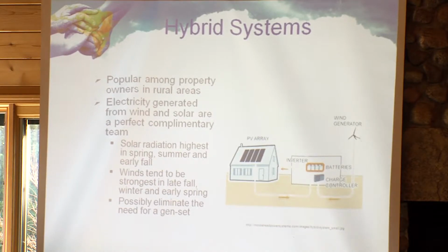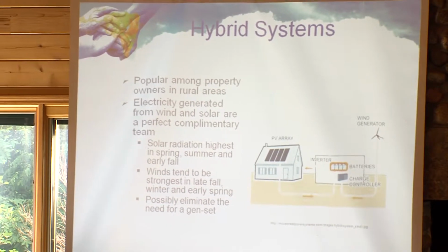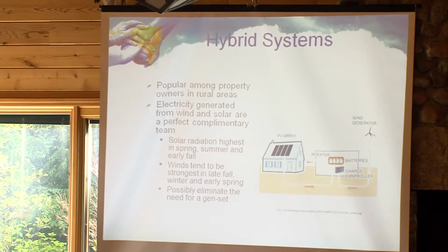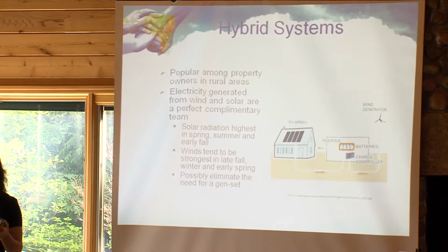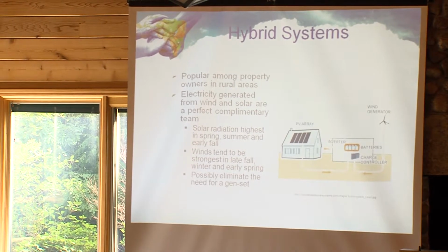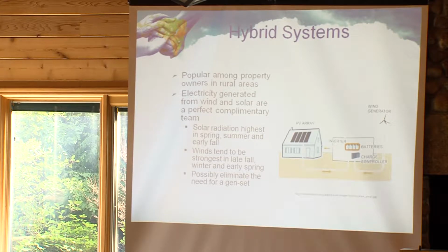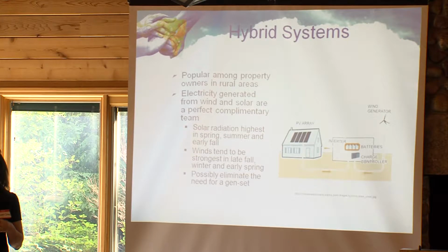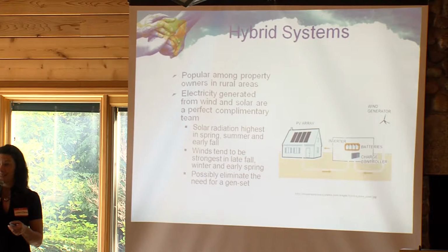So this is sort of that perfect marriage where the sun is stronger during the day. It's not shining at night. It's windier at night than it is during the day, typically. So it's a perfect marriage to harness both of those forms of renewable energy. And then again, if you have critical load that you don't want to lose during a power outage, or if you just need to make sure that you're okay in the event that it's not windy and the sun's not shining, the battery bank is a good investment. It's a wonderful hybrid system. It is costly.